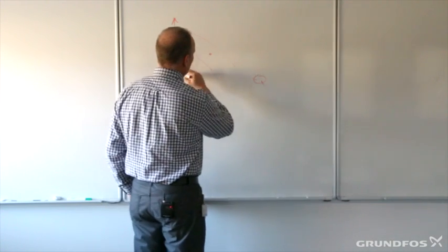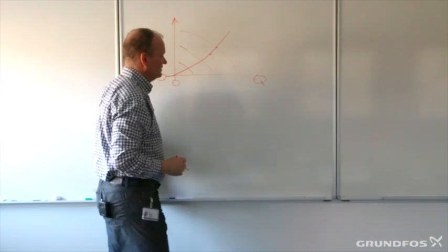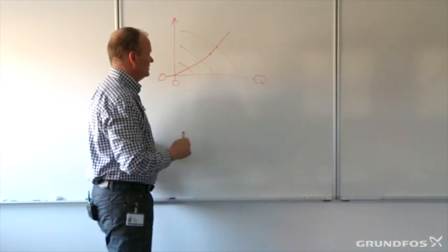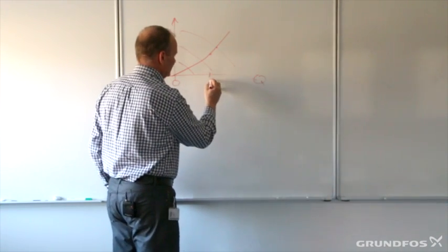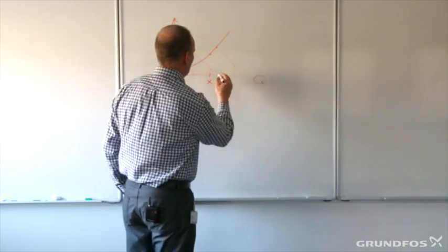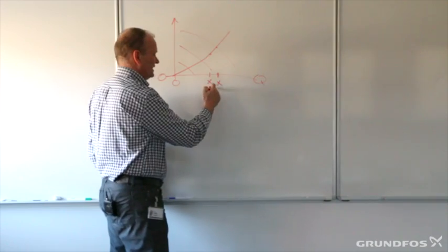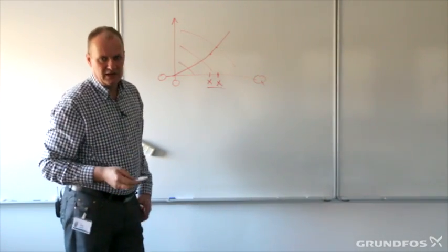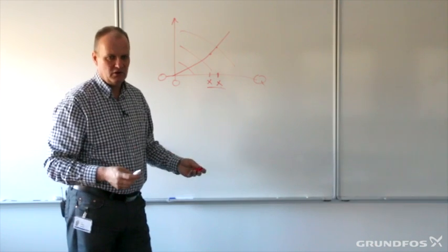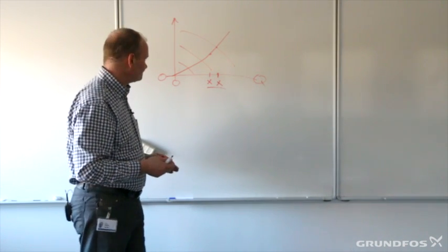then if we do nothing, what will happen is that the system characteristic will most likely look something like this, which means that instead of having the pump deliver exactly the flow we need, it will deliver slightly more, meaning that the conditions for our cooling coil, our heat coil or whatever will not be as intended.